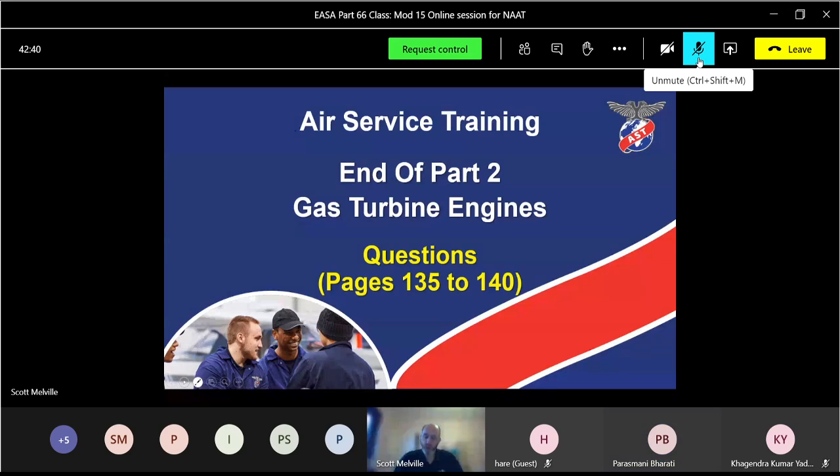Okay, give me some requirements that an engine lubricating system must have. First of all, cooling, lubricate, and prevent corrosion. Yeah, all good stuff. Not too bad. Resistance to oxidation. Yeah, oxidation. Now with oxidation, what